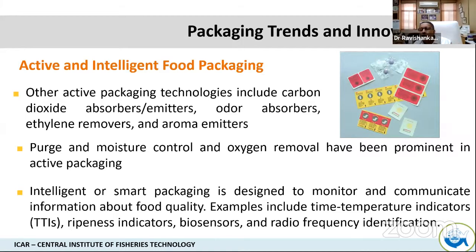You put a small sachet. I'll tell you, you buy any of this cashew mithai from Haldiram. I'm sure somebody must have noticed. You open that, kaju katli or whatever, there is a sachet. It is actually an oxygen absorber. It's hardly 1 or 2 rupees, whereas it will double the shelf life. So this sort of intervention we can definitely introduce. Only thing is you need a laminated film. You cannot use an ordinary polyethylene or polypropylene film. You may have to spend 1 rupee extra for packaging material.